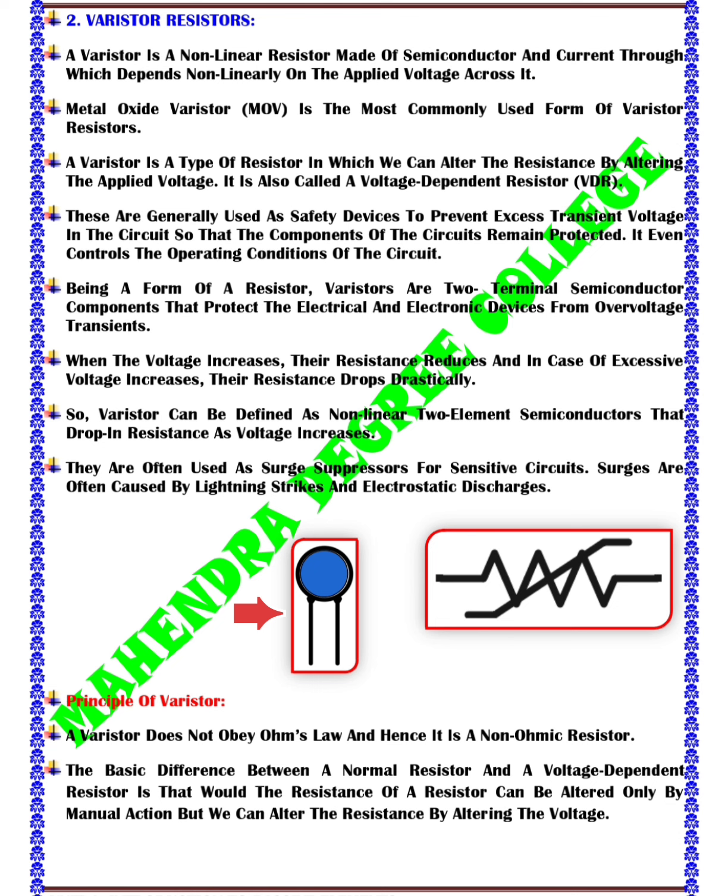The varistors are typically constructed using a ceramic material, often zinc oxide (ZnO), with small amounts of other metal oxides. The ceramic material is sintered into a compact structure, which creates a network of grain boundaries.